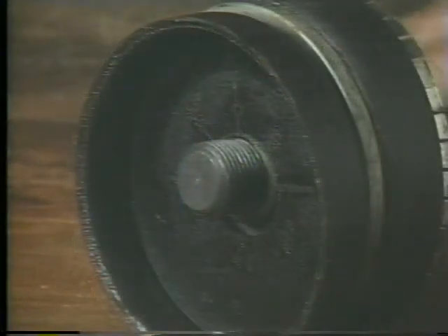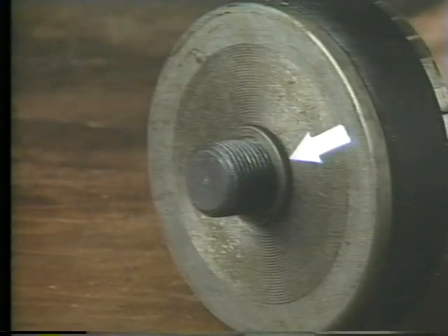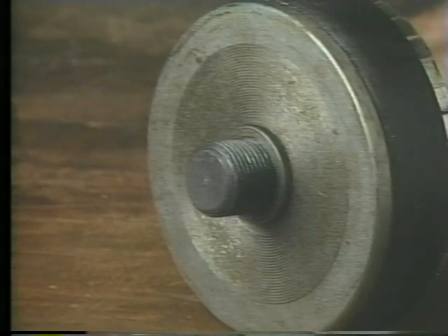The cup packing is a stiff, cup-shaped piece of material, often made of leather. The cup leather is saturated with a high-temperature wax that seals the leather, making it airtight. Over a period of time, the leather can become brittle and crack and allow air to escape between the cup and the cylinder wall. When that happens, the cup packing must be replaced. A spacer fits into the center hole of the cup packing to protect the inside edge of the packing from damage during operation.